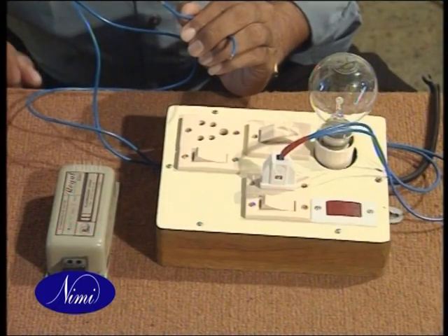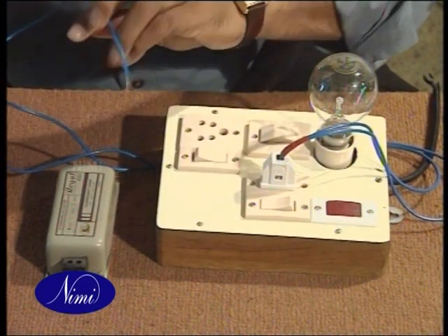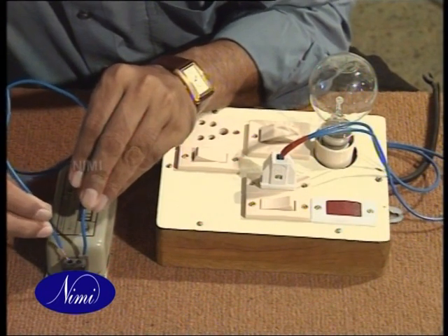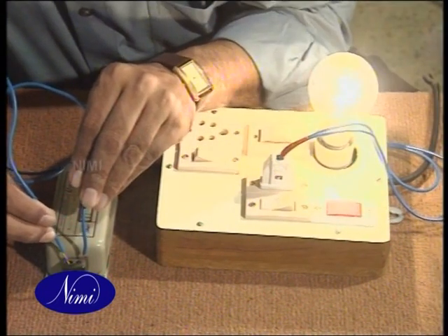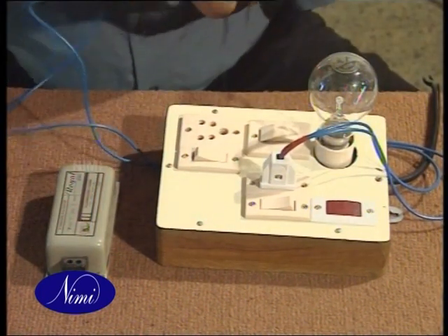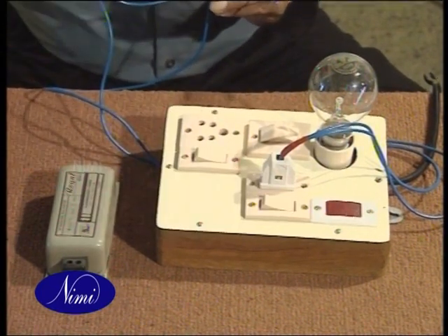They are affected by both high and low voltage. The more often a fluorescent lamp is turned on and off, the shorter will be its lifespan. To check whether a choke is open, connect it to the test lamp in series. If the lamp glows, it means the choke is okay. If the test lamp does not glow, then the choke is open. If found defective, replace the choke with another one of the same capacity.